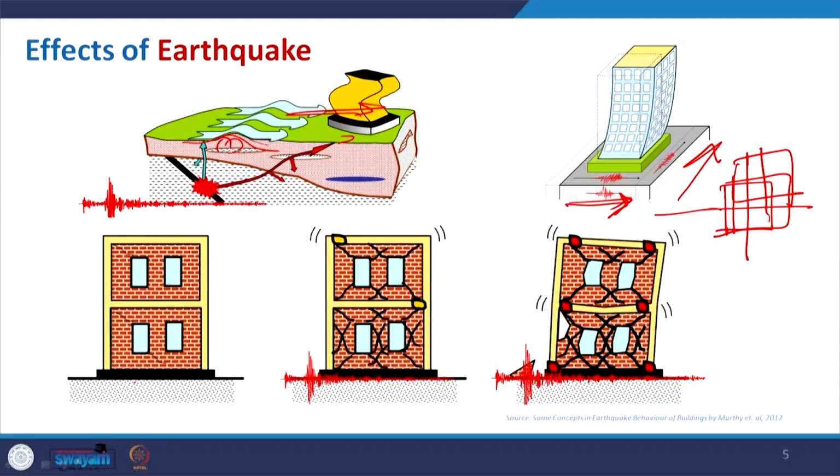Now, if you see it carefully, the example here is the same building, and this is with a very minor earthquake. Here you can see in detail that some cracks developed at the corner of this window. Also remember this: whenever your building materials have joints, where two materials meet, those portions are vulnerable.